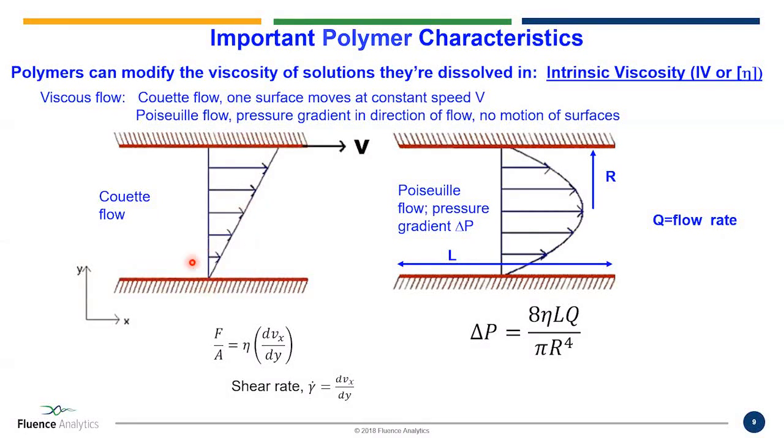And so then the liquid has a stick condition here, it has a stick condition up there, so you'll have velocities going from 0 to this big V, and that gradient is called the shear rate, the rate of change of velocity with respect to this y coordinate. And what relates it is the viscosity, a proportionality parameter. The bigger the viscosity, the more pressure it takes to achieve that velocity, the more viscous the liquid.